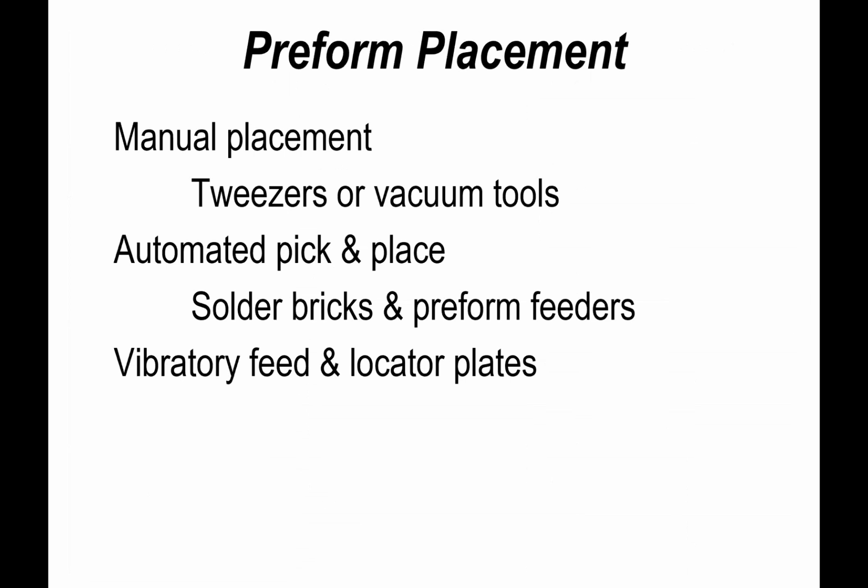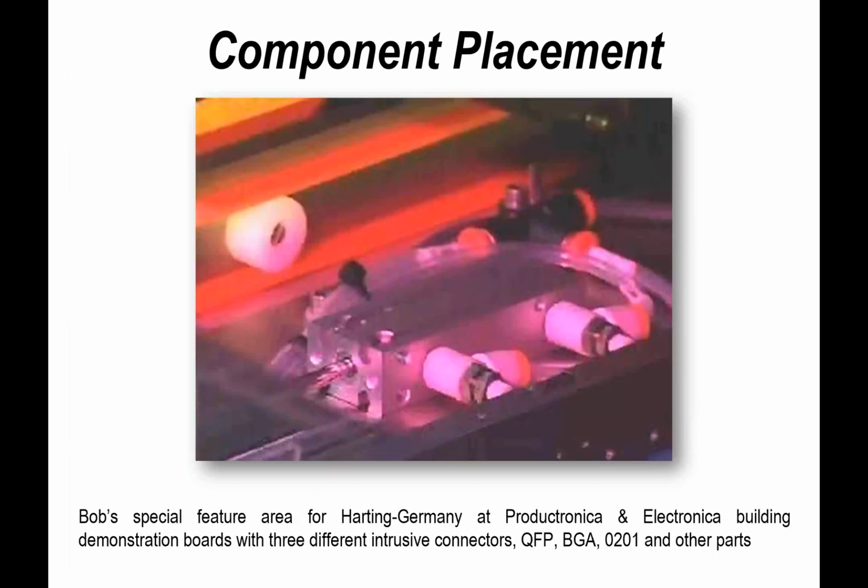Again, you've got to consider automation, how you're going to automate the process, but in terms of the solder bricks, they're normally in tape and reel feed, and a variety of different sizes are available, and they specifically can solve a design problem quite often, and that's one of the advantages of that technique. We have feeder mechanisms, vibratory feeders and locator plates, which are available from different suppliers. But you've got to make sure you pick the right material and also think about what other aspects of the process you need to control, which we'll mention as we go through.